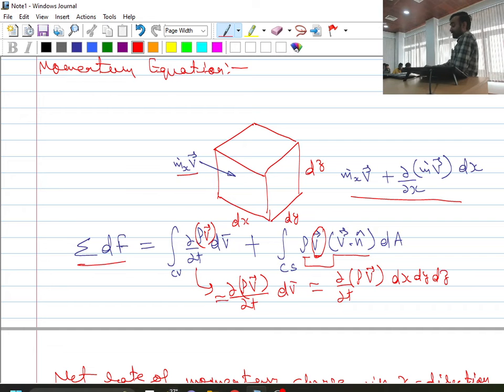The necessary condition for the mass flow rate is that you must use only the normal component of the velocity to the interface, but whenever you are considering the momentum, you have to consider the total momentum which is entering at the x. Is this point clear? V vector dot n cap represents the velocity perpendicular to the surface area, so there it will be the component velocity. But ρ into V, that V will be full, because that is a simple V vector. It is not multiplied with the normal. Fine. Is this point clear?